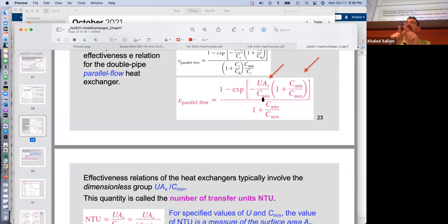It's not really that greedy. Its m dot Cp is just like one kelvin or something. m dot is kilogram per second, and Cp is kilojoule per kilogram kelvin. You multiply the two together, the kilogram cancels, and you get watt per degree C. So you give it this many watts, and its temperature goes over the roof.